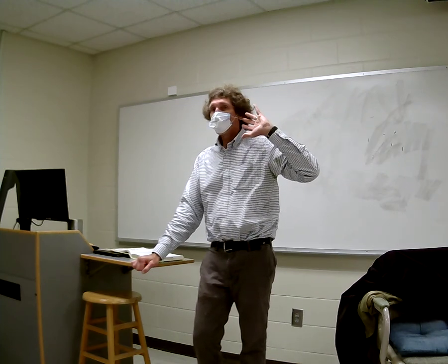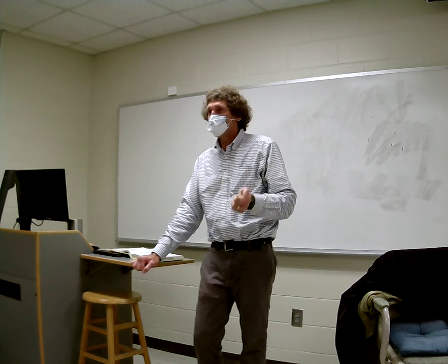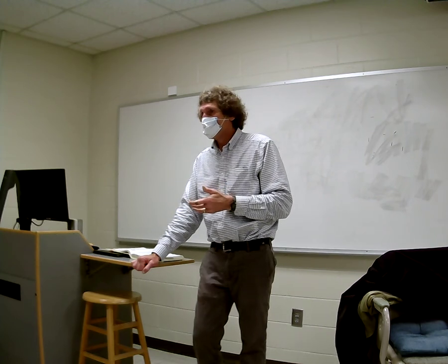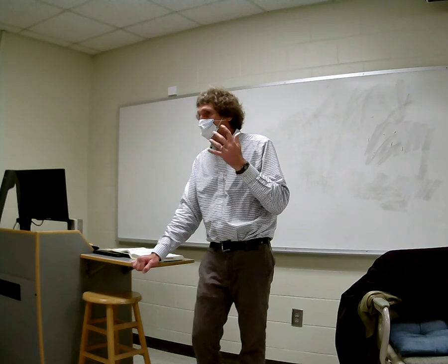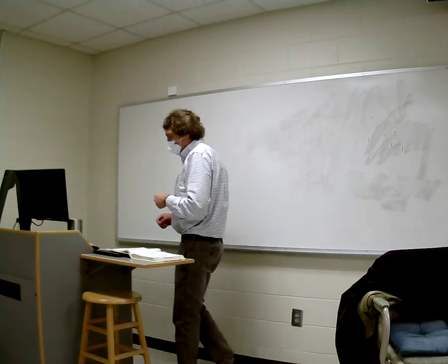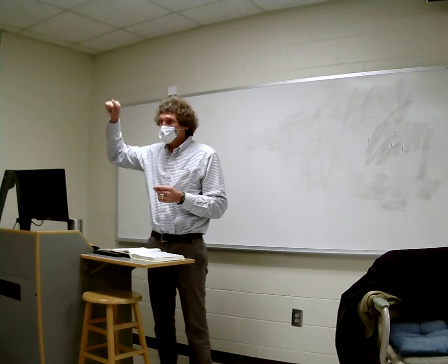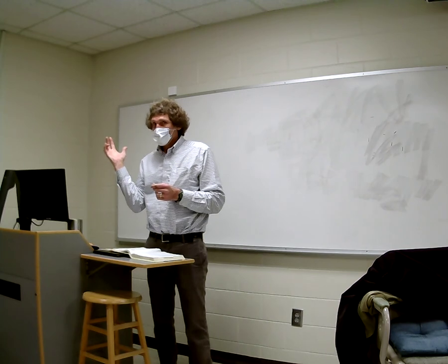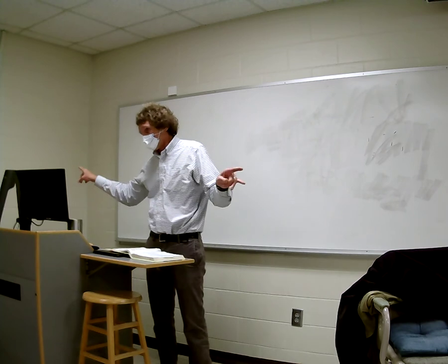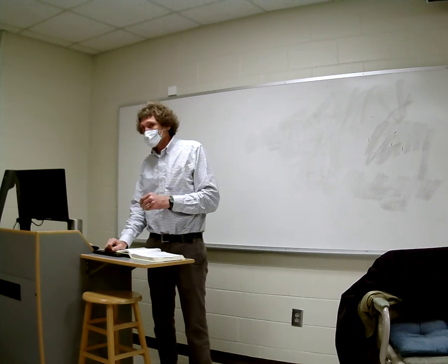Does anybody ever remember, if you put on an AM radio or anything that had amplitude modulation and turned on a hairdryer, what happened? Y'all remember that? Anybody notice a hairdryer causing AM radio to beep? Has anybody been in a car that had the old plugs, driving down with the AM radio on, and when you accelerate, you hear it in your speakers? Well, that's mainly, can't say for sure, conducted emissions. Through the walls, the hairdryer for sure. That through the electronics of the car. That's the stuff that I teach how to mitigate.